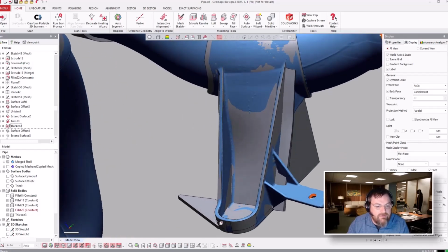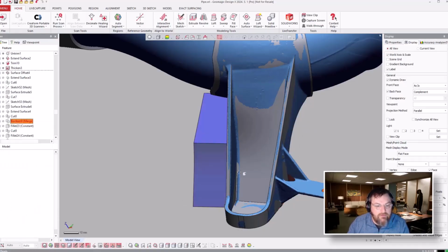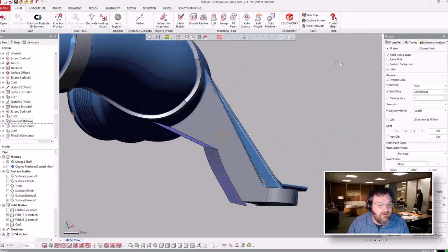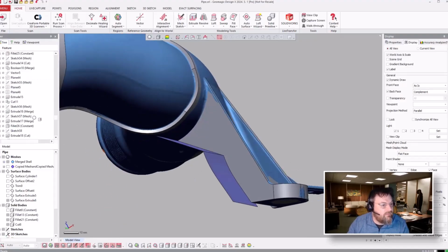So they went ahead and extruded this because that was one straight extrusion. They fit a surface there and then extended it all out. And now we're just going to trim everything back from all the different directions and boolean it in. So we're just going to trim all the pieces off with all the surfaces, even on the back, and trim it all in. So from here, I think the rest of it is kind of self-explanatory for this one.